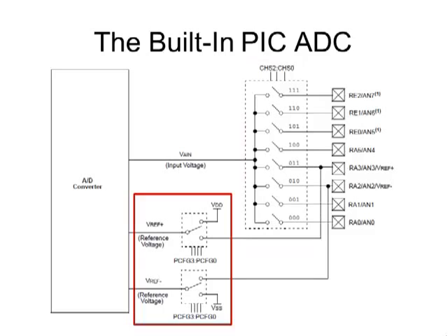I can also have different types of reference voltages. So here I see a couple of single pole double throw switches that are built into the chip. Okay, and I see a couple of port configuration bits. There are 4 port configuration bits, PCFG3 down to PCFG0. Okay, those define the different possible states of those 2 switches. So you can see that I can use VDD, that's my supply voltage for the microprocessor itself. So that would probably be my 5 volts. I can use VDD and VSS for my signals.